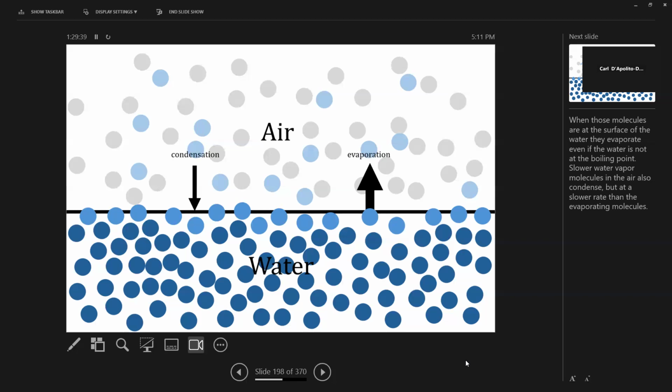So you can cool the air just by spraying water in, because then the water evaporates and that takes energy out of the air. Essentially, evaporative cooling is just like an air conditioner, except it also humidifies. You just spray water into the air, the water evaporates, vaporizes. As it vaporizes, it takes an extra amount of energy to vaporize, so that heat becomes no longer feelable. When you talk about something blowing over water, like a lake or through a fountain, that's what's happening. Some of the water is evaporating, and that cools down the air.